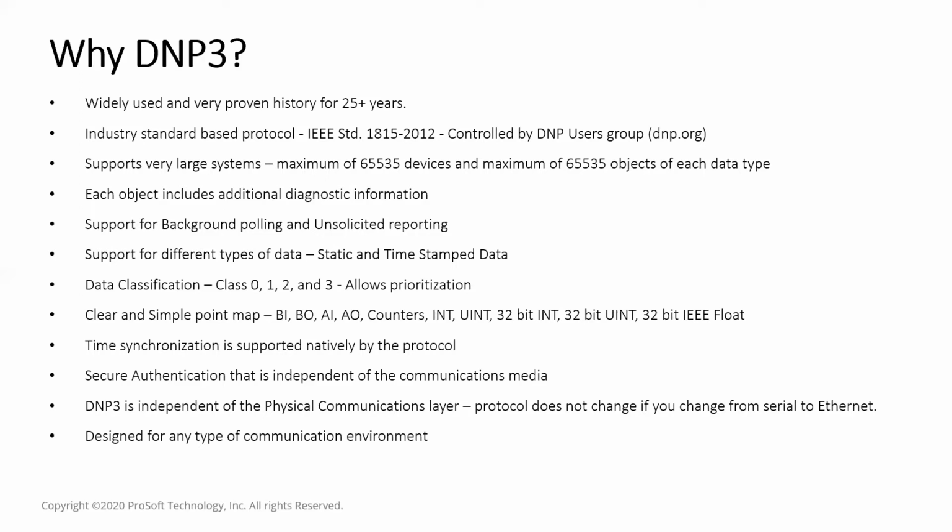I told you how scalable it is. The other advantage of this protocol is that it does include a fair bit of diagnostics, and the biggest use for that is in helping with things like predictive maintenance. One of the biggest things with this is that it's a timestamped protocol. So any event, any alarm condition that happens, you've got a time and date stamp, and all of that information can then be brought back to a SCADA host for analysis.